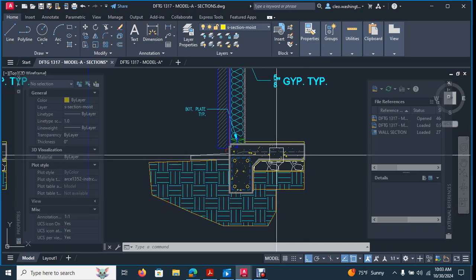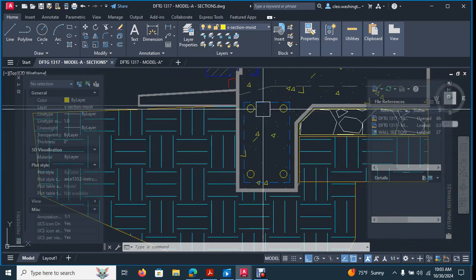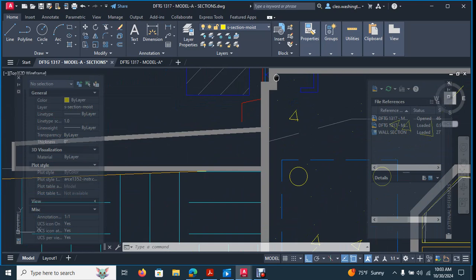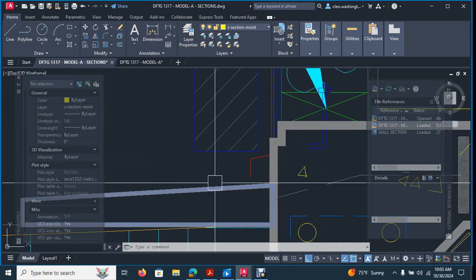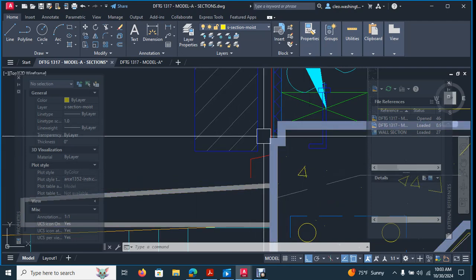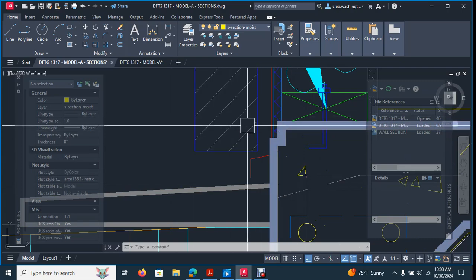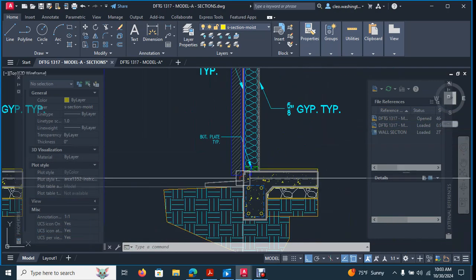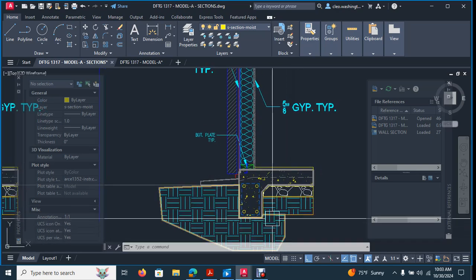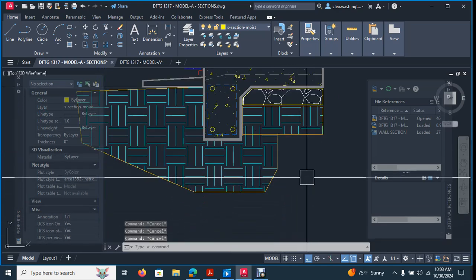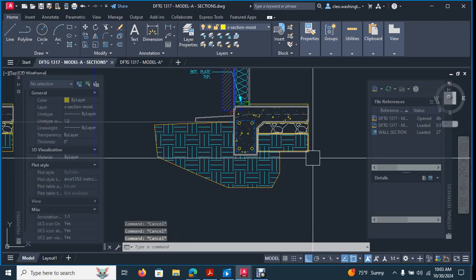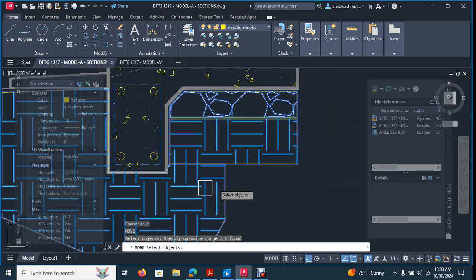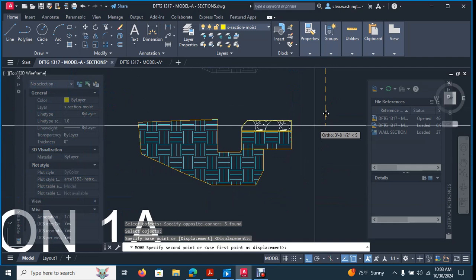Now, what we need to do here is we need to make a modification at the exterior slab edge, because what's happening is we have to have a dap out here, okay, that actually shows how the brick is actually sitting on this dap out ledge. And I know that's foreign to you guys, so just stick with me and we'll go ahead and show you guys exactly what I mean when I say dap out. So let's go ahead and move all of our hatch properties here. Let's move them down 20 feet.